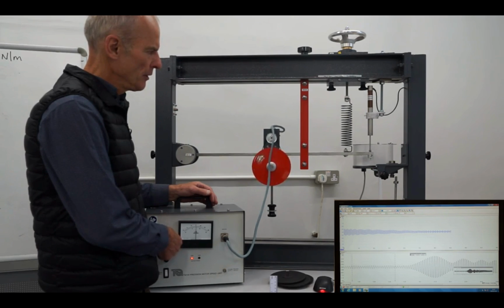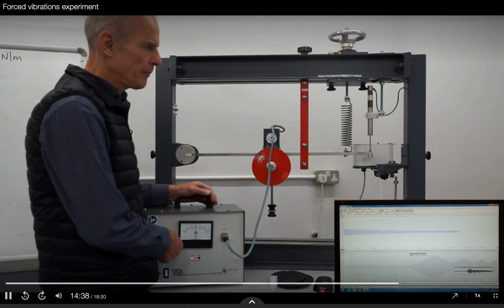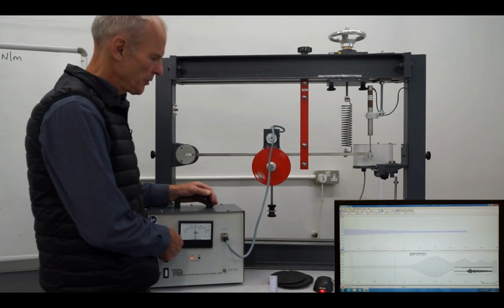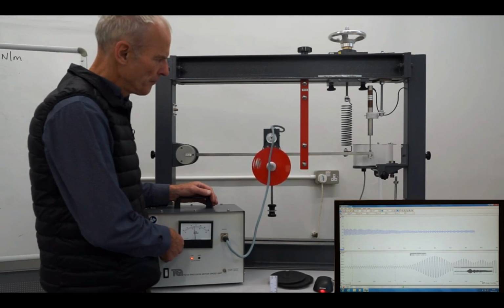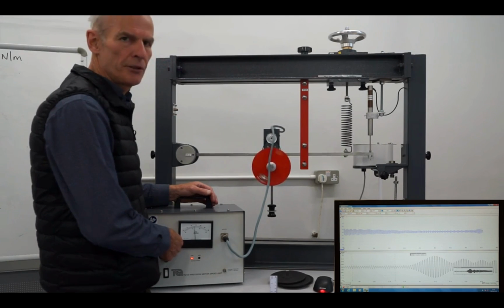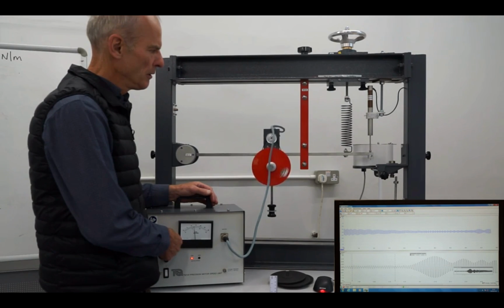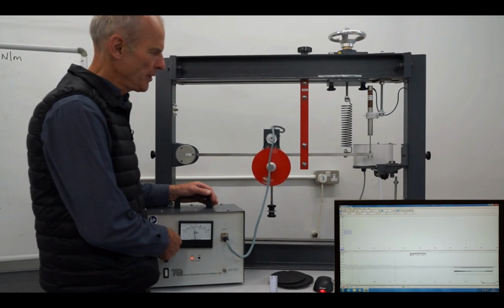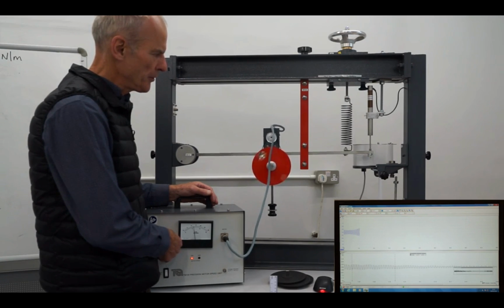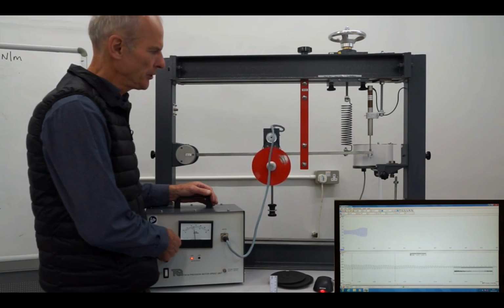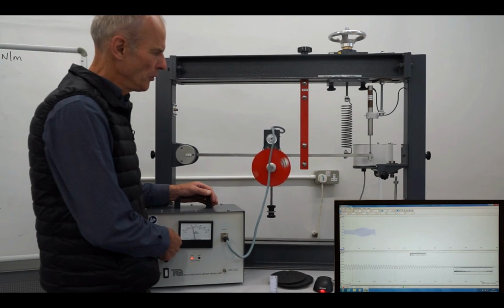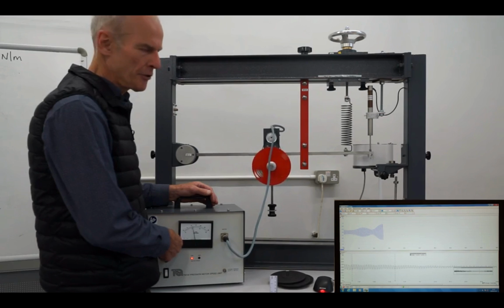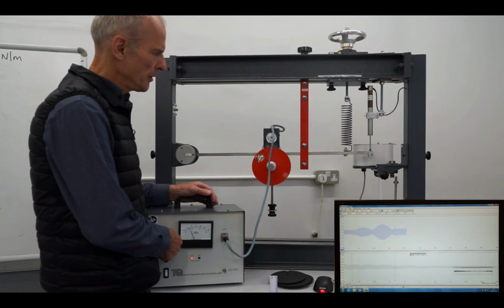As we come down, you can see this beating phenomenon is coming up again, and as we decrease it, we've got a larger amplitude of vibration, and we can sometimes sweep straight past resonance, but we may just hit it. So when you do these experiments, you can see now it's getting a larger amplitude vibration. And if I decrease it more, we're getting even very close to resonance now. And if I come down, I can avoid all of that. And it's just rocking away.